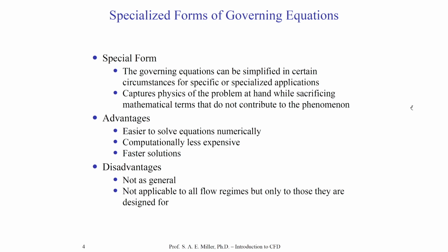You shouldn't download a CFD code and apply it to a particular type of flow or problem outside of its range. For example, you would probably not use a CFD code designed for hypersonics for a creeping flow. That example is obvious, but they can be much more subtle when you start looking at specific equations and solvers.